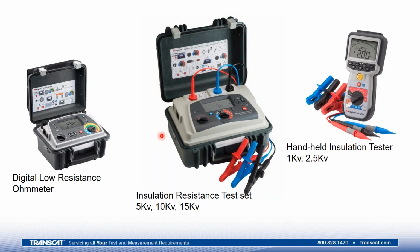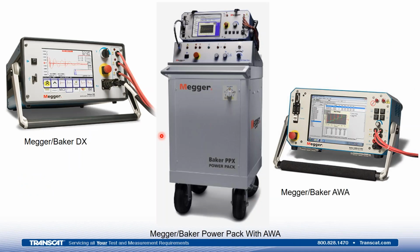Other useful tools I want to mention that Megger has to offer for testing motors are the DLRO, or the Digital Low Resistance Ohm Meter, for doing bar-to-bar tests on DC motors, and the MIT series insulation resistance testers to check the insulation resistance from phase to phase and from phases to earth or phases to frame. With Megger's acquisition of Baker, we also now offer these units that do the famous Baker surge test. Transcat does carry these now as well, so you can feel free to request a quote if necessary.